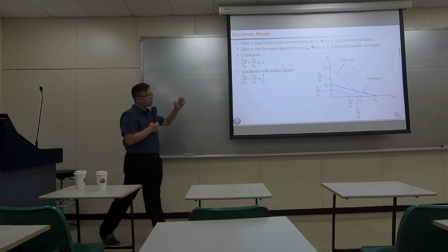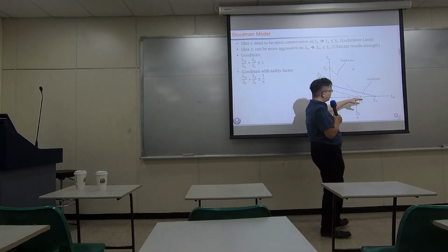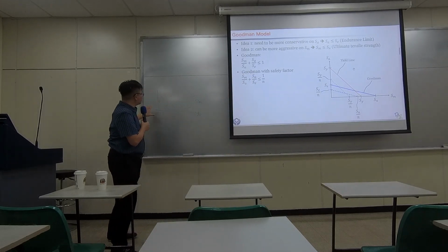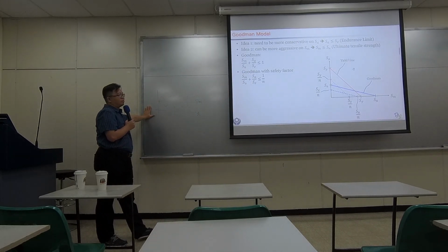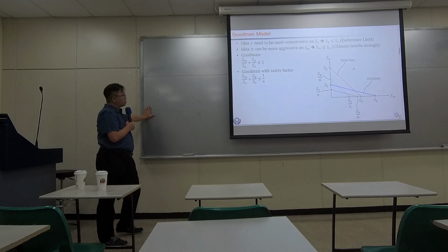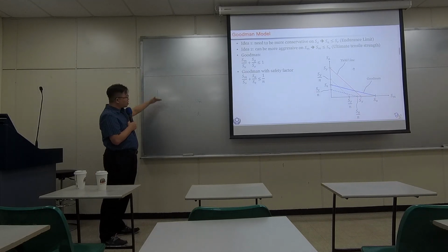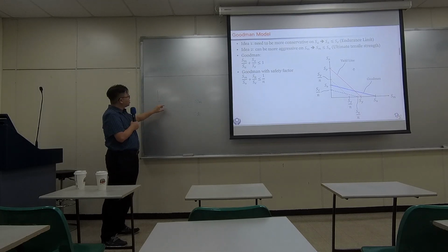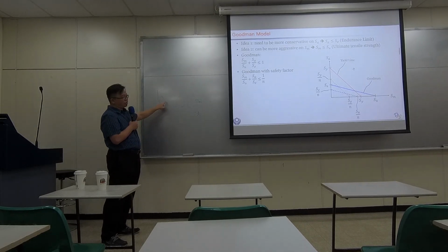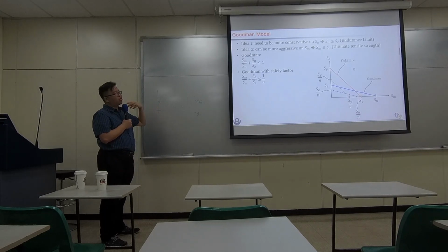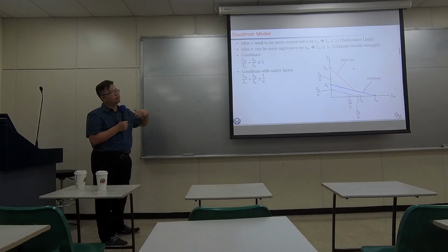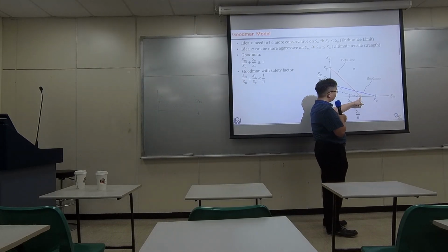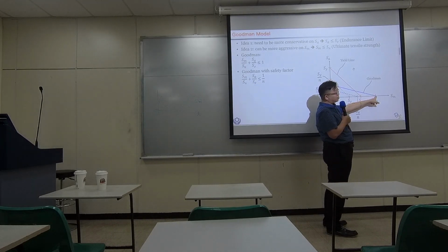Okay, if you only focus on the mean stress, and then you take a look at how the dynamic stress is being applied to the material, in fact, because of the fluctuation, many times the stress is actually lower than the mean. So Goodman believes you can actually enlarge your mean value a little bit.